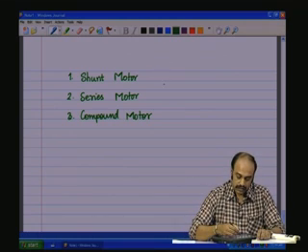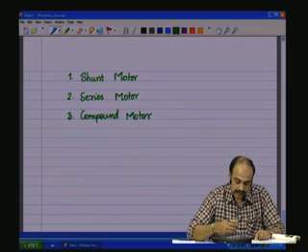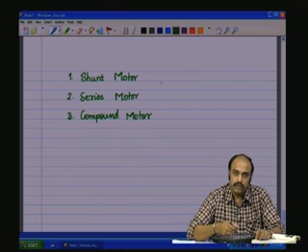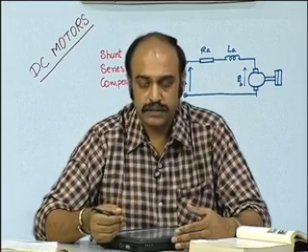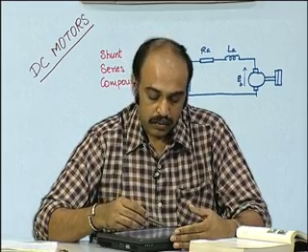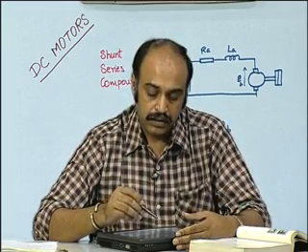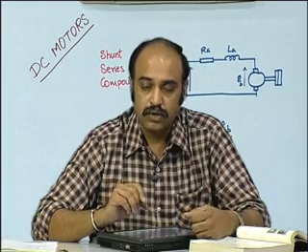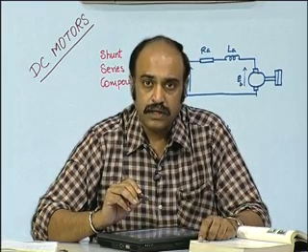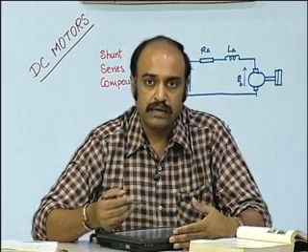There are various benefits and disadvantages of each of these. We will have a look at these in the next session. Each has its own unique torque speed characteristics, which are useful for certain applications, and thereby we try to use a particular type of motor for a particular type of application, because the torque speed curve gives an idea of whether that particular motor can handle the load. See, the generated torque speed curve and the load torque speed curve will give you an idea of which type of motor can be used for a given application.